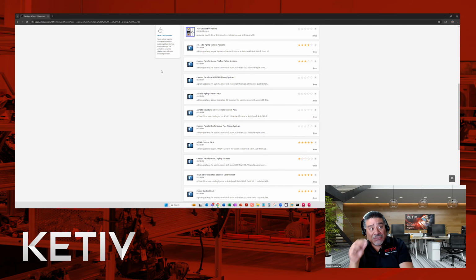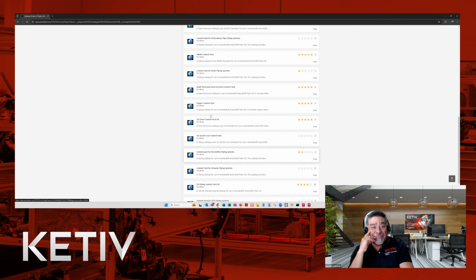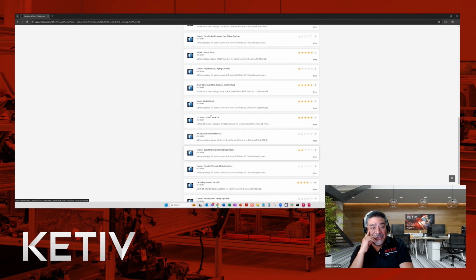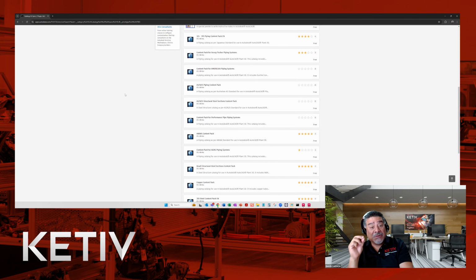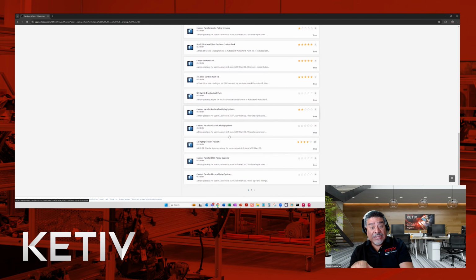Now, these do not come installed with Plant, because if they were to install all of these, it would just take way too much space on the install process and probably take longer. But you can come here and you can download these. So there are some additional things here that you might want to look at first before thinking about custom components, because it might already be here in this location to where you could find it instead of having to create your own, like Vitaulic fittings here.